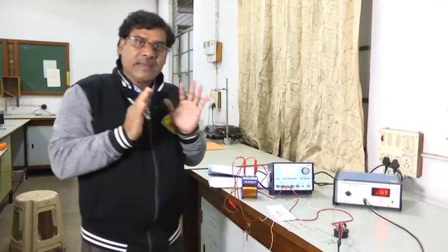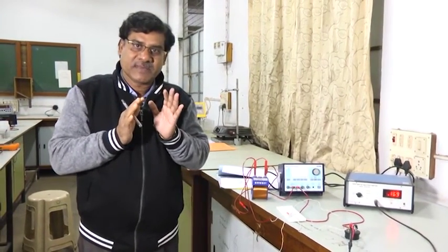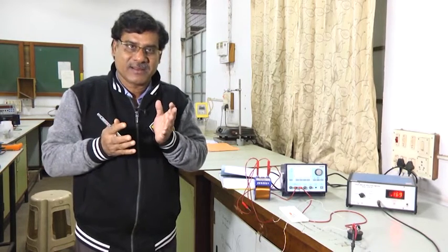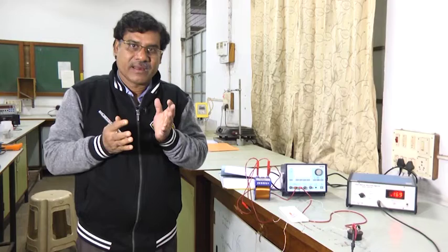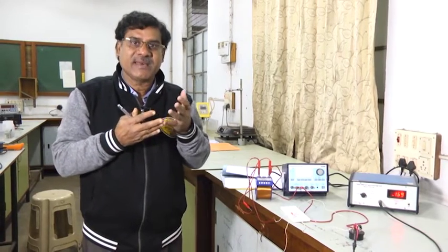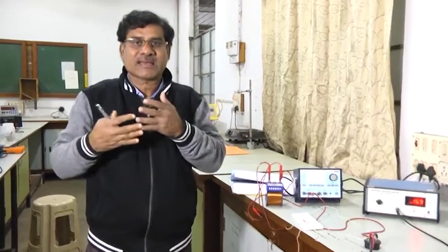Now, in resonance condition, XL equal to XC, that is the condition, right. XL and XC are reactances. So, I into XL is the VL, I into XC is the VC. So, XL equal to XC means VL equal to VC. So, at resonance condition VL has to equal VC. That I want to show you.